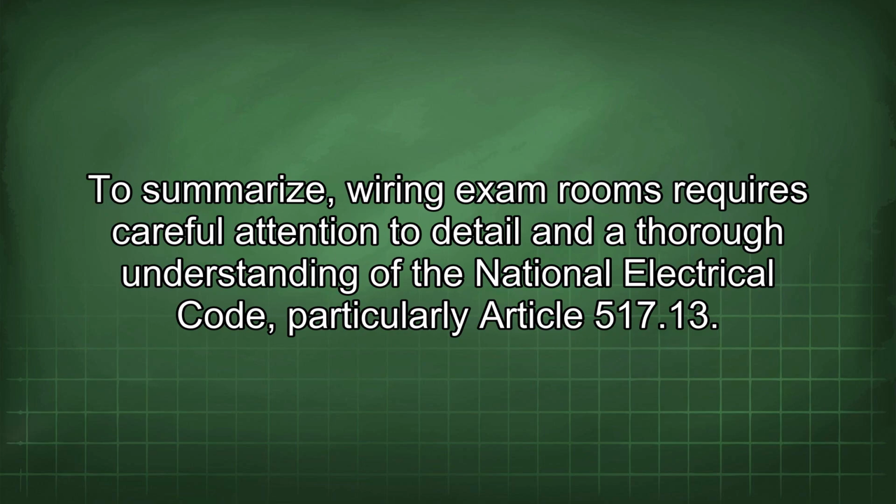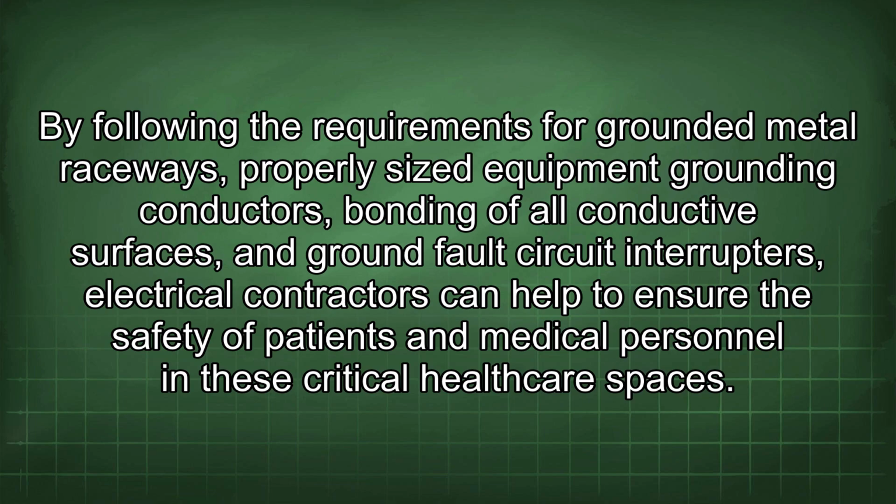To summarize, wiring exam rooms requires careful attention to detail and a thorough understanding of the National Electrical Code, particularly Article 517.13. By following the requirements for grounded metal raceways, properly sized equipment grounding conductors, bonding of all conductive surfaces, and ground fault circuit interrupters, electrical contractors can help to ensure the safety of patients and medical personnel in these critical healthcare spaces.